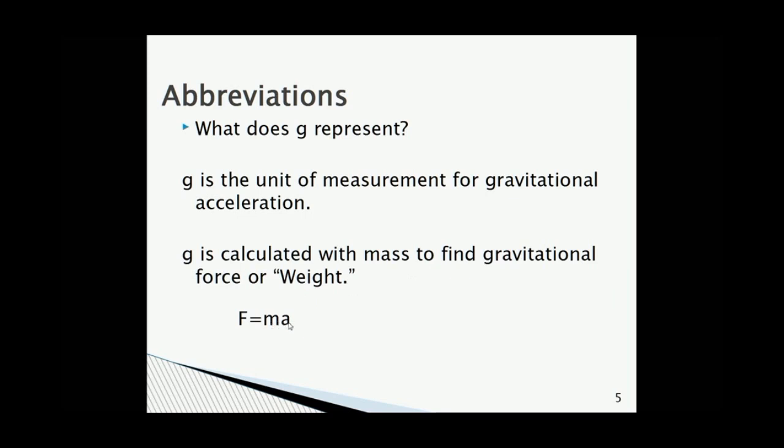What do I mean by sum of the masses? Well, in this case, we are not doing a simple object mass. We are doing a stack of multiple different objects with varying masses. You have an armature, which has its mass. You have a slip table if you're performing a horizontal test and its mass. You have the fixture for your test specimen and its mass. And you have your test object's mass, or your unit under test.